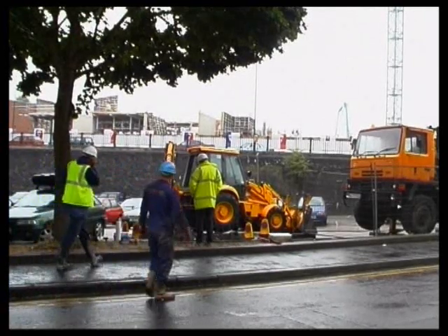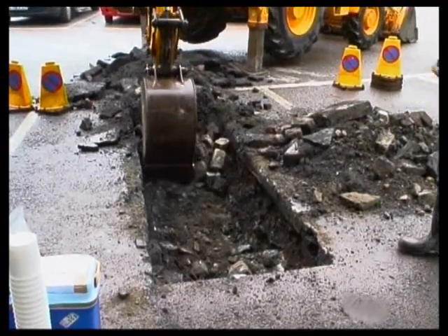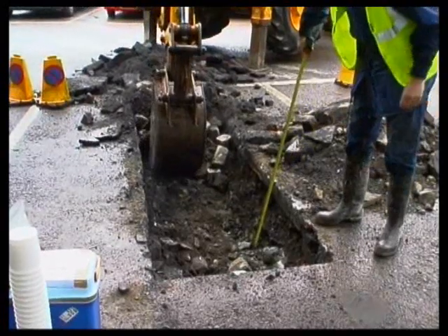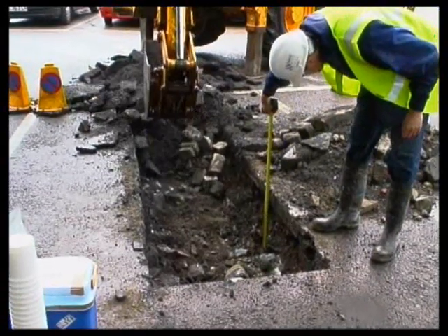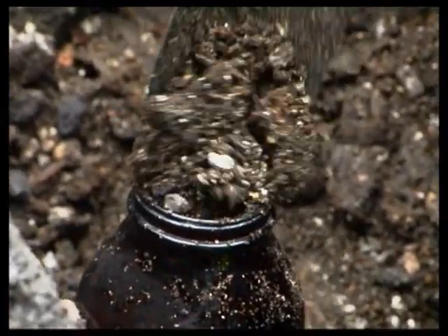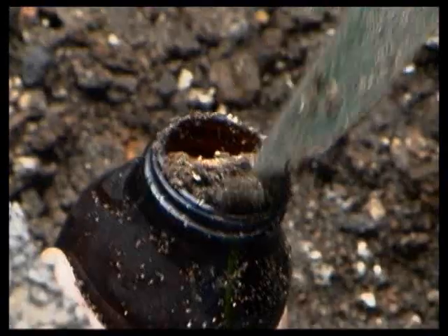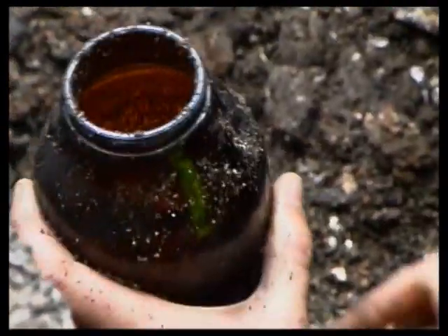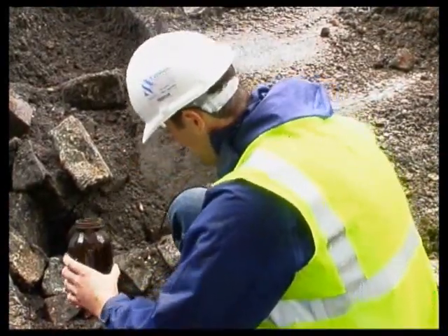The trial pits to assess the ground conditions don't normally have to be deeper than 4 to 5 metres, unless specific problems are encountered. Samples of subsoil can be taken away for analysis, and engineers can determine the nature of the various strata by inspecting and measuring the sides of the pit.